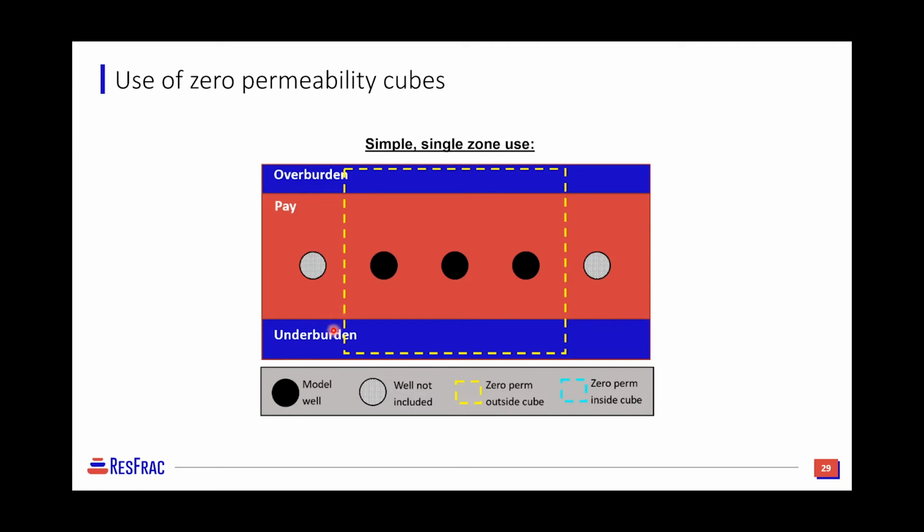Hi, Dave. So yes, if you had wanted to, say you set all 5 of those wells up, you could actually set the wells up to deplete that zone, but then that kind of goes against using the zero perm cube. So you can't put it in there depleted. You'd have to frack the well and deplete it as a normal well. That would be a bigger model is what I'm getting at. So yes, you can create that depleted zone, but you can't input it as depleted already.